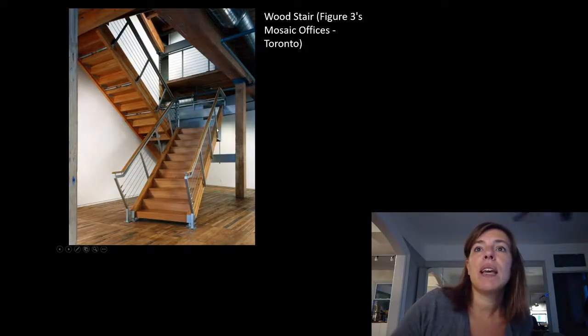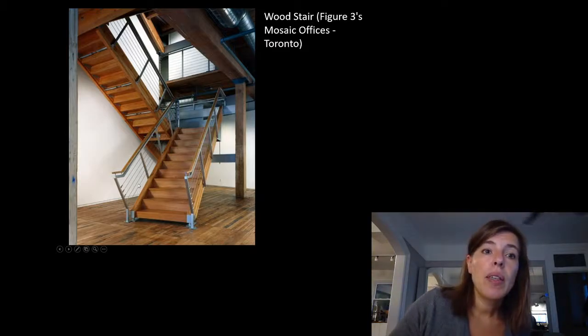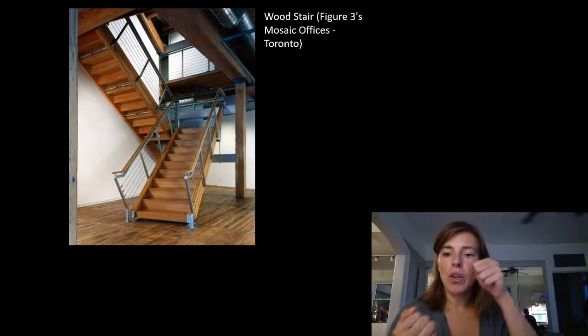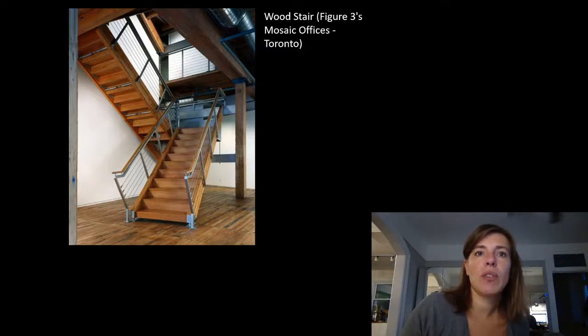This is the one that Dave showed you that he did. So this one, we've got a handrail and top rail. We've got our posts, our pickets, our cables. So you can see that that's 4 inches and that's 4 inches. They actually did this at tighter than 4 inches. And those cables needed to, when you tried to push a ball through, not separate so much that the ball could go through under a specific load.